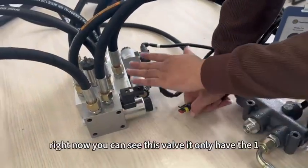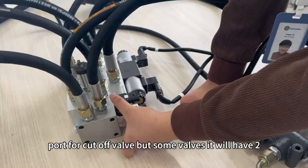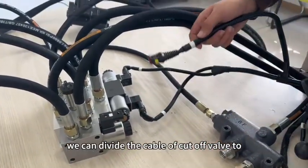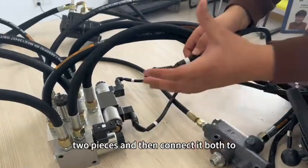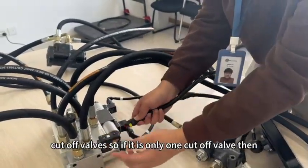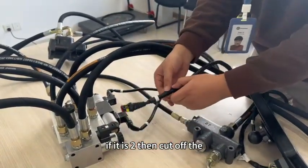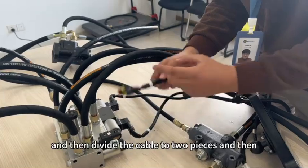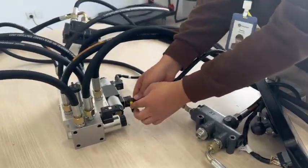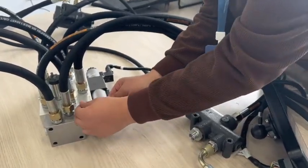Right now you can see this valve only has one port for the cutoff valve, but some valves will have two ports for the cutoff valve. We can divide the cable of the cutoff valve into 2 pieces and then connect it to both. So if it is only one cutoff valve, one port, then directly connect it. If it is 2, then divide the cable into 2 pieces and connect it to both ports. Okay, we connect it like this.